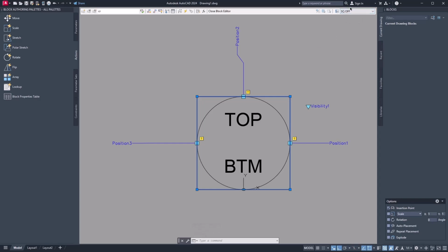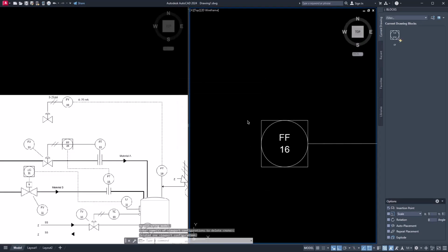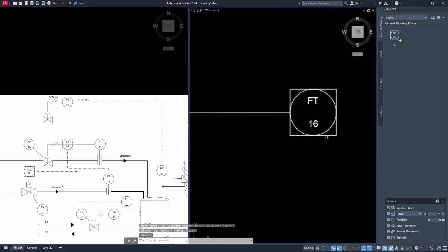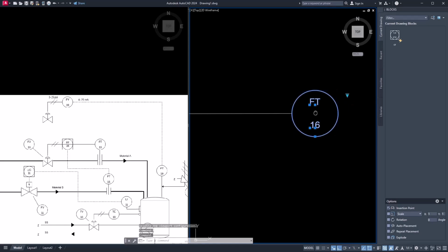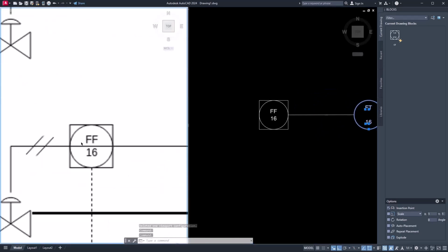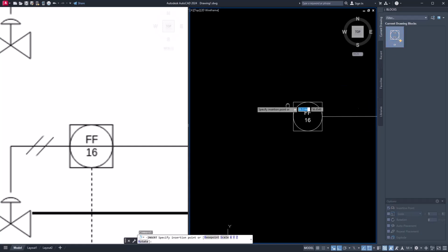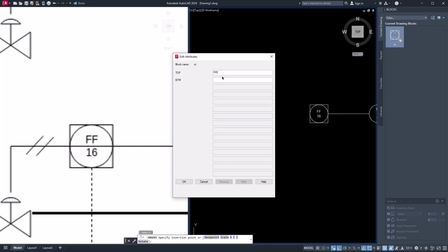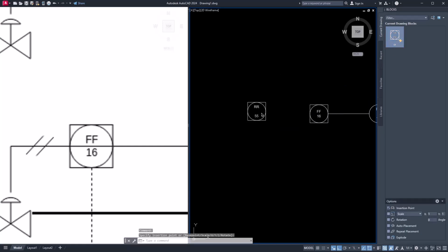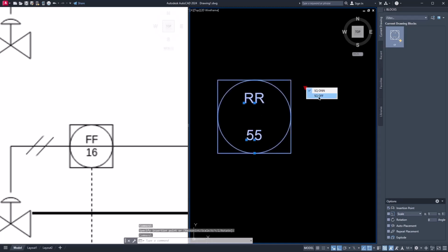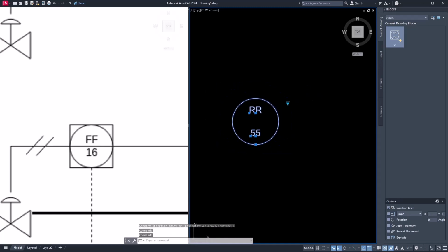Now what we're going to do here is hide this square when the square is off. So just select square off here and select the square. Now you can make it invisible. Now the square is turned off. Let me close the block editor and see the changes. Right now in this case the square is on. Now if I select it, you can pick square off. I'll show you one more thing. If I place it here, with some random values, and pick the option called square off, you can see the square has turned off.